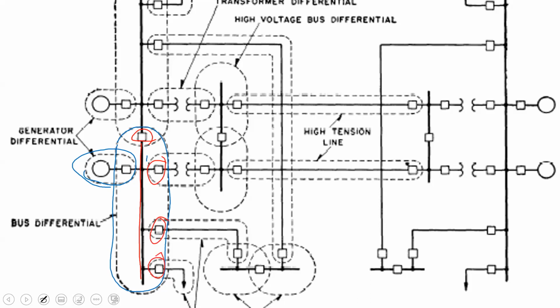So these breakers that you just circled, these would be the breakers that are delayed. In other words, they wait and see if A star operates. Yeah, so these would be delayed. Yes. All right, so the fault would move from being a generator fault to becoming a bus fault.